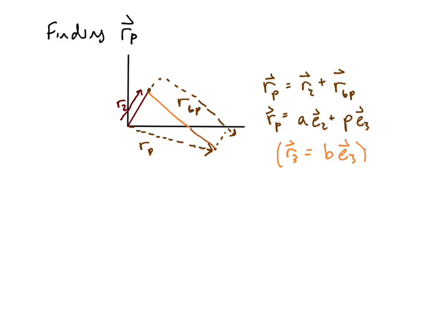And then instead of RBP, we could say that's equal to the constant P times E3, where E3 is in terms of cosine theta 3, sine theta 3. So those are quantities that we're able to find out. Because we're able to find them out, we can find RP. So all of this is doable. We can handle it. But when we want to find our analysis for every position, we don't want to manually calculate everything for every point on this link. So we're going to find out that MATLAB is a much easier way to go through this. And we will do that right now.